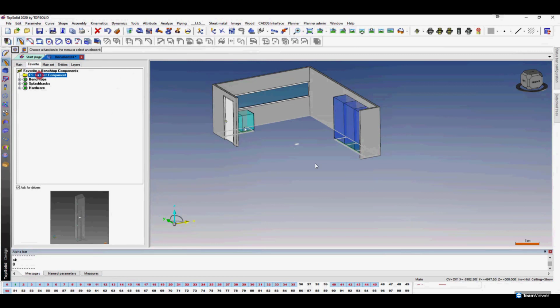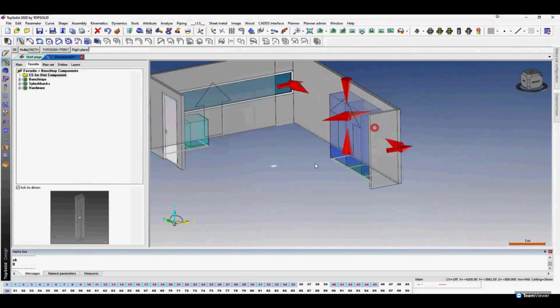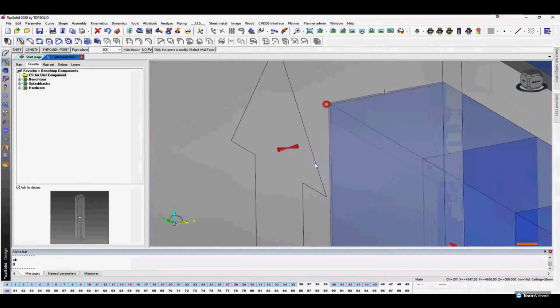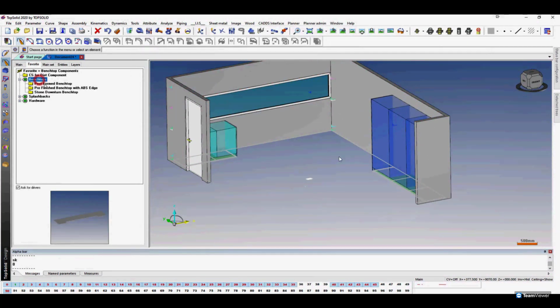When I go to our benchtops, coordinate system distribution, I bring in the driver block and then I offset it from one side because the benchtop isn't going straight between walls. It's going against one wall, finishing against another benchtop. These benchtops in the distributed component library already contain your mason's miter and your toggle bolts, hence the reason why we're using these library items. So if I just pause it there.